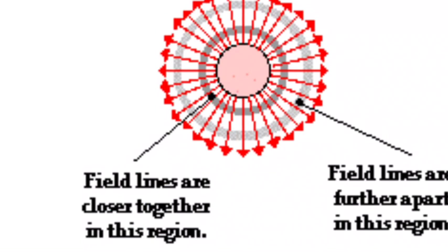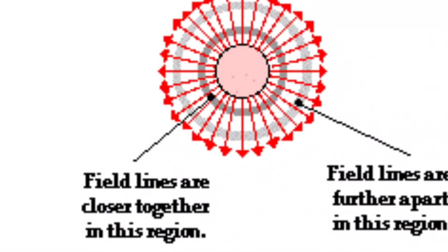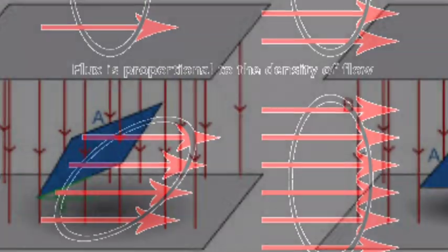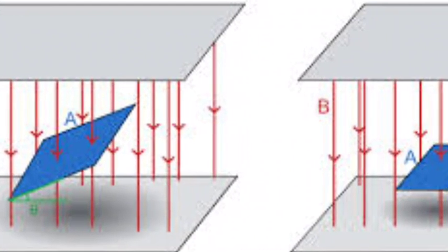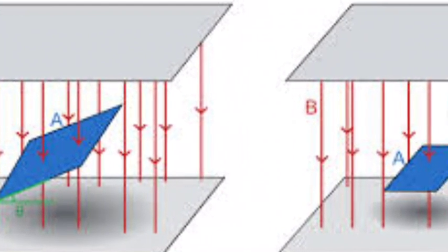Magnetic lines have flux. Flux is the total number of field lines in the magnetic field. It is measured in Webers. In more technical terms, magnetic flux is the magnetic field strength normal to a surface multiplied by the area of that surface. How many lines pass through an area is denominated as flux density, measured in Webers per meter squared. This way we may mention that magnetic field strength is equivalent to magnetic flux density.